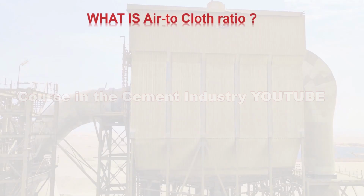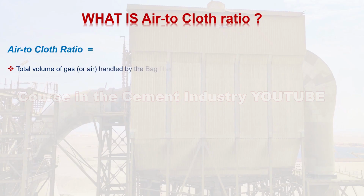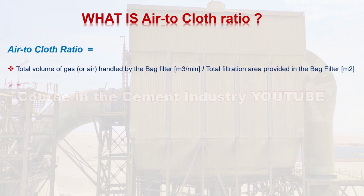What is air-to-cloth ratio? Air-to-cloth ratio equals total volume of gas handled by the bag filter, cubic meter per minute, divided by total filtration area provided in the bag filter, meter square, equals cubic meter per minute divided by meter square, equals meter per minute, a velocity unit.